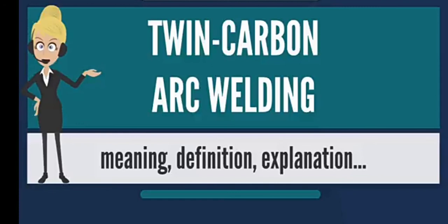Twin carbon arc welding, though more complex than single carbon arc welding, possesses the advantage that the arc is independent of the job and can be moved anywhere without getting extinguished. Moreover, the workpiece is not a part of the electrical circuit.